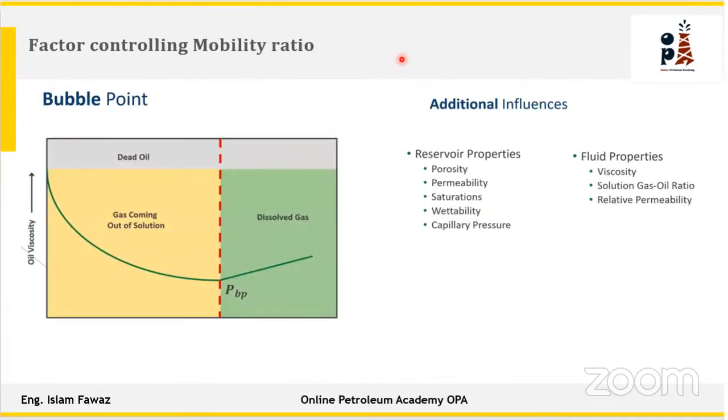And also when you ask the question, what is the best time to start water injection? The best time to start water injection is at the bubble point pressure. Why? Because if we look at the viscosity and the pressure here, this is the point at the bubble point pressure. This is the maximum volume at the bubble point pressure, and the gas is not liberated from the reservoir, because if we have gas in the reservoir, the gas is very compressible. You are injecting, but you do not see any response because the gas is highly compressible.